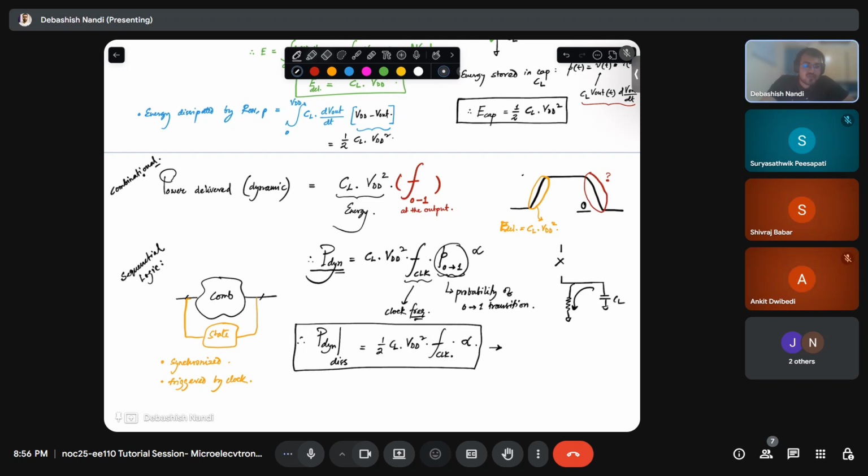Yes, sir. So if you increase your heat, understand this very carefully. You are at room temperature, 300 Kelvin. Now you are increasing your clock speed. That means the power being dissipated from the resistance is increasing, right? That is converting to temperature because your energy is proportional to kT, right? 3 by 2 kT. If you take 1 degree of freedom, then it is half kT.